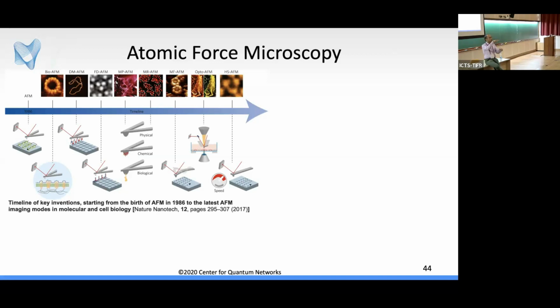Very good. So, atomic force microscopy, the idea is that you measure a rough surface. You have a scanning tip. It's a cantilever that you scan across a surface. And as that scanning tip moves, you bounce off a laser. And as this moves up and down, the reflected laser does this. And you measure it with a camera. And from that displacement, you can estimate the roughness of the surface.